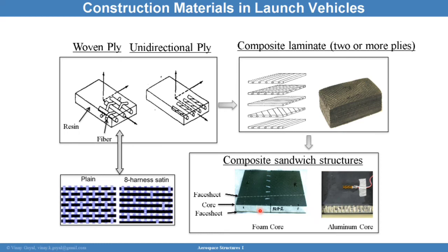If you double that thickness h, the moment of inertia increases by 8 times, 2 cubed. As a consequence, the bending stiffness goes up by 8 times, which means I have a more robust structure that can resist bending. If I didn't have that core and brought the face sheets together without it, the bending resistance is much lower.